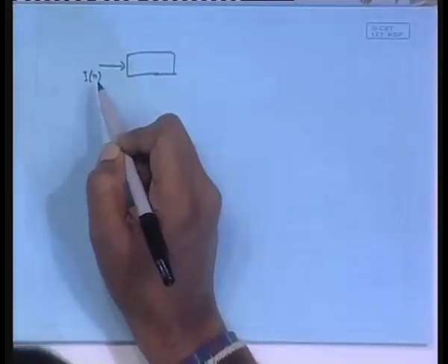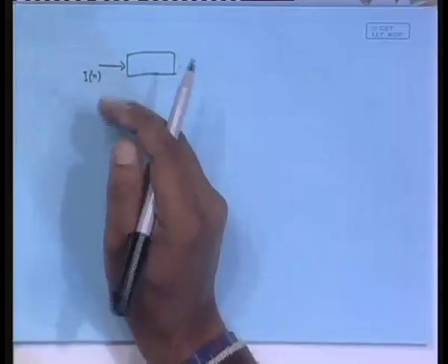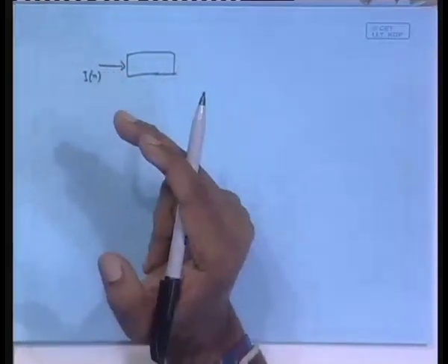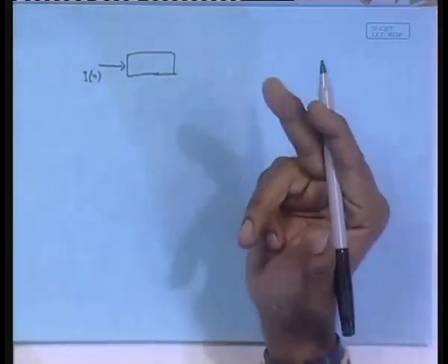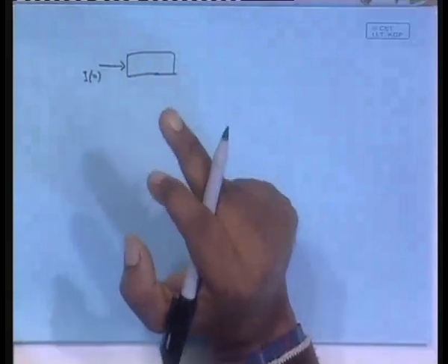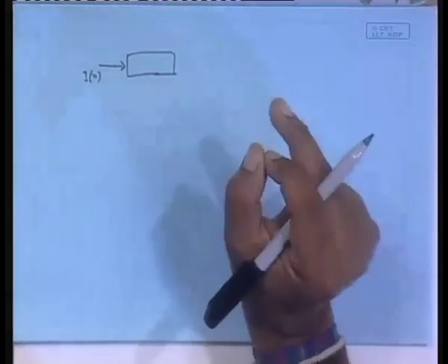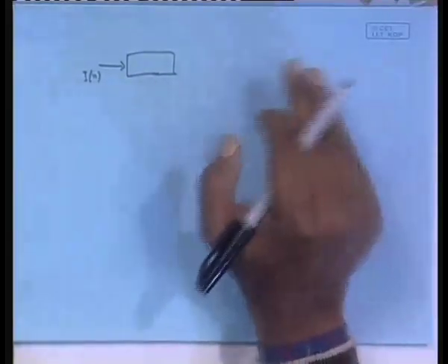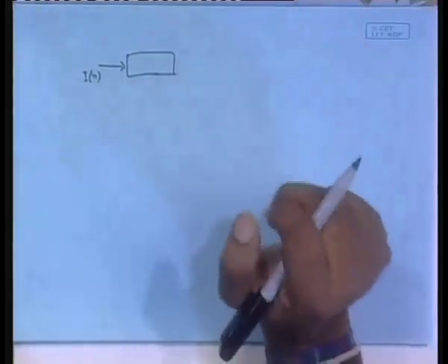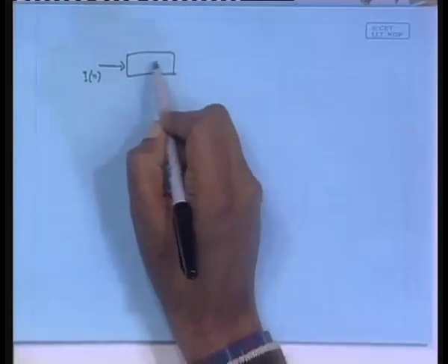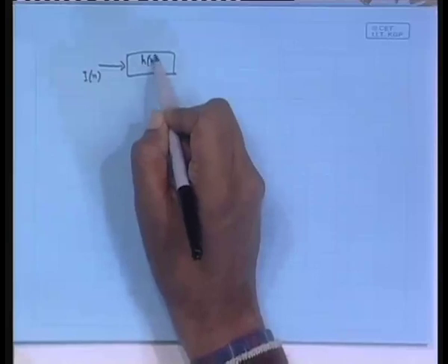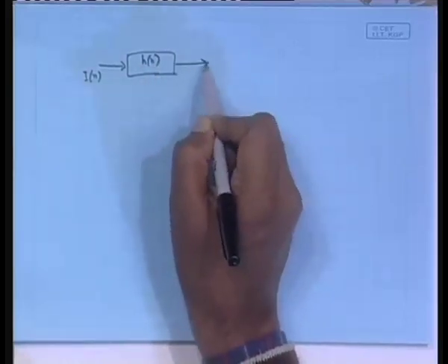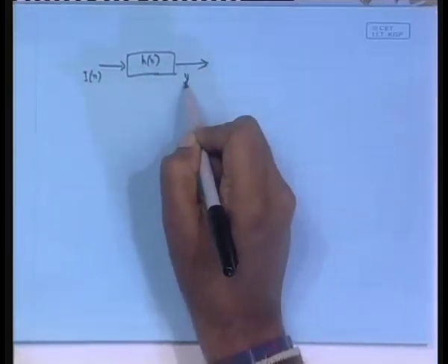These I0, I1 can take some discrete values from a set of finite discrete values. That set is called the alphabet. It has a finite number of symbols. If you are taking r bits together, then 2 to the power r symbols are possible. In general, this could be complex, with in-phase and quadrature components, but for our business here, we assume this to be real. And in I n, there is then an equivalent discrete time model of the channel, which we replace by H n. And what you get here is Y n.